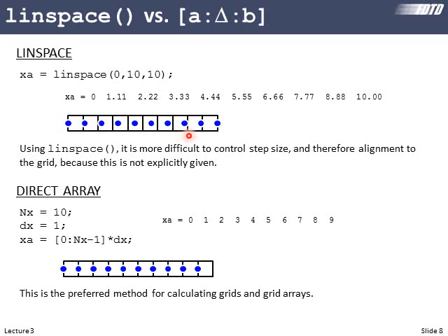And you'll notice that the data does not really conform exactly one per unit cell. They're offset a little bit, and it's very easy if we have a grid that we want to model something on that's 10 by 10. They usually would be much larger. If we create our axis arrays with linspace, something like this could happen where we're accidentally telling our algorithm the position of those points is not exactly where we intended it.